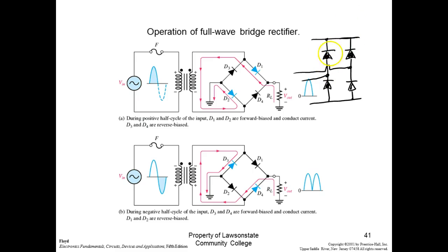Up here, the anodes are pointing back toward the source, so this would be plus. Here, the cathodes are pointing back to the source. That'd be my DC. This is the exact same circuit. If you look right here on our AC, your AC should always see an anode, cathode, and notice my AC down here, my other one sees an anode, cathode. So these are not in parallel. This is a lot easier to draw. But notice what happens when this is positive and this is negative.